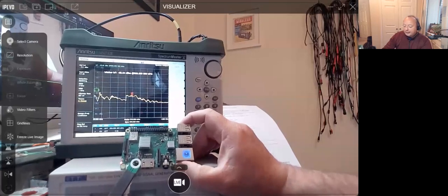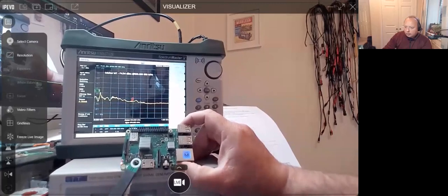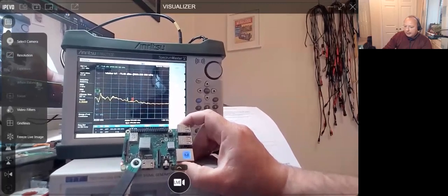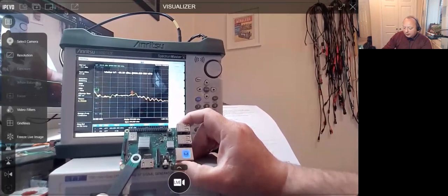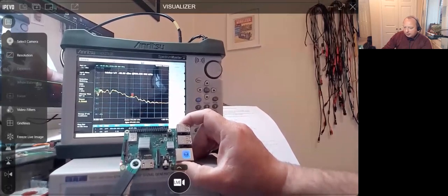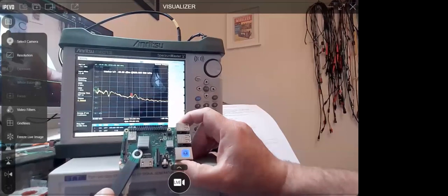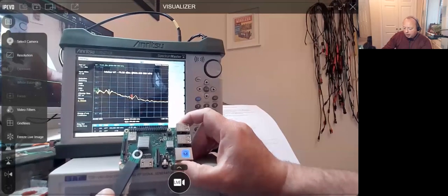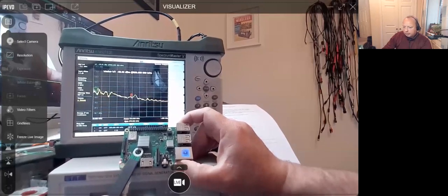So it's interesting. So we've proved it here, the search coil is right over the inductor, and of course that is singing like an absolute canary. So you're absolutely right, Reece. Look at that. So all over this area around here, which is the power management, that is where it's super noisy. So that could be hushed up. That wouldn't be too difficult to quieten up.